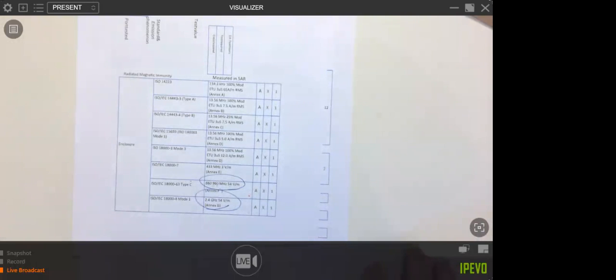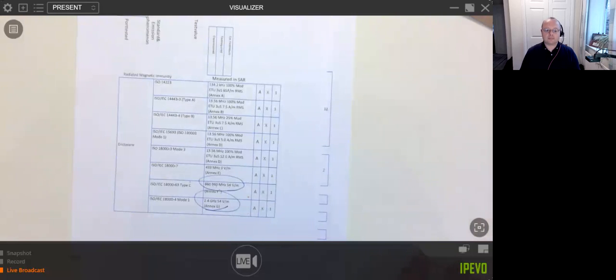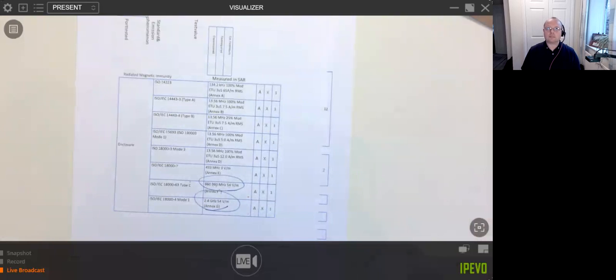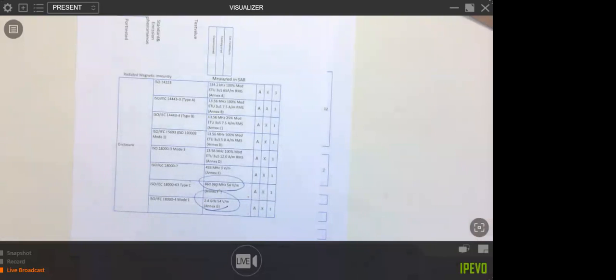So let's say you expose some bit of electronics to 10 volts per meter. If you had 2 plate electrodes, one grounded and one at 10 volts, and they were a meter apart, I presume that's a 10 volt per meter field. And then you stick your electronics somewhere in the middle and it doesn't blow up.